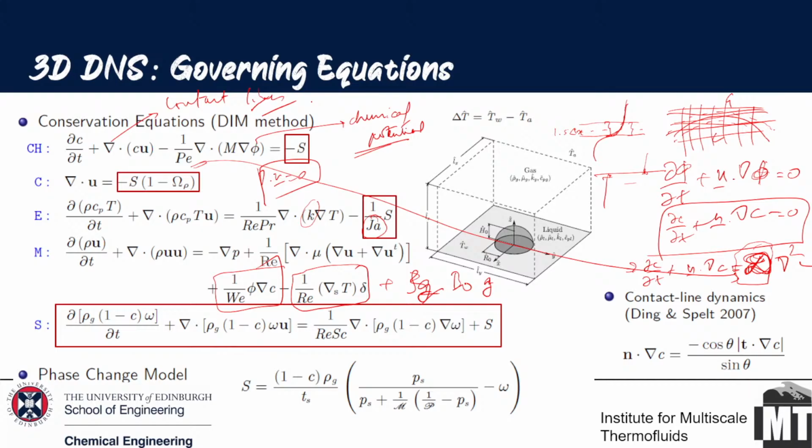So if you have a lot of density change, then I would have considered the Bond number. But in this case, it's not of a great value. We also account for the fact that if you heat a liquid, the volume expands, but we found that in this case it's very, very small, so we just ignored that. So obviously, this is what is happening in the momentum equation for the liquid as well as the gas